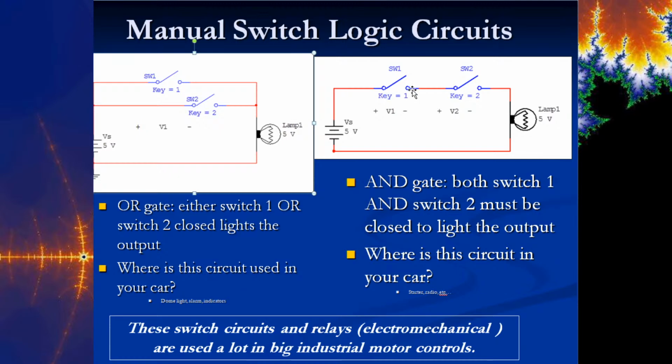Because the combinations are off, off, off, on, off, or on, on. And the only one of those 4 combinations that makes this turn on is the 1, 1 situation. Over here you have 0, 0. That'll keep it off. But what if you have 0, 1?